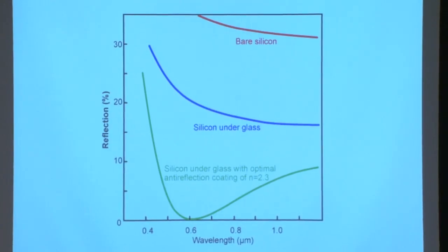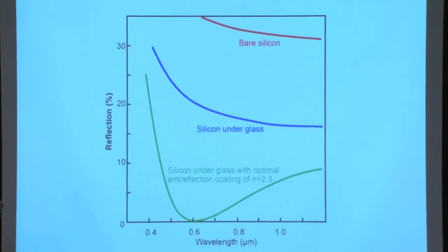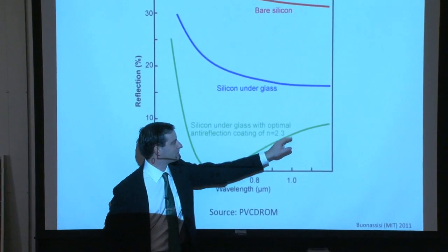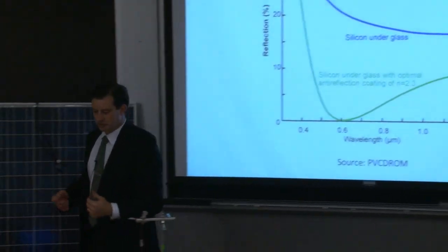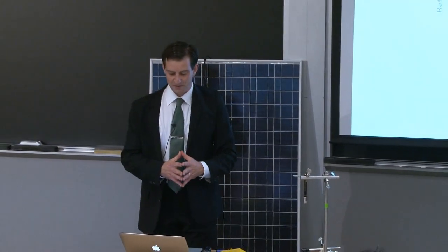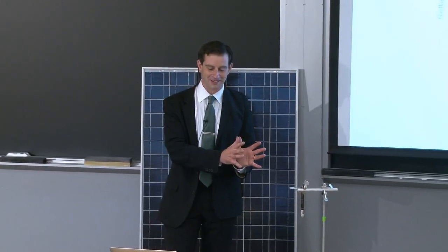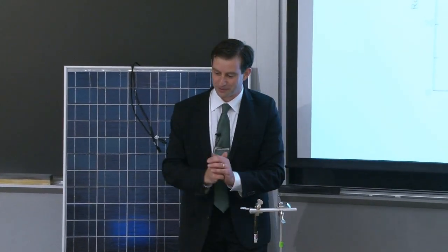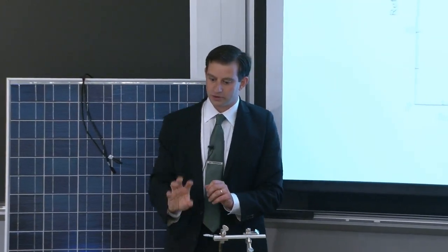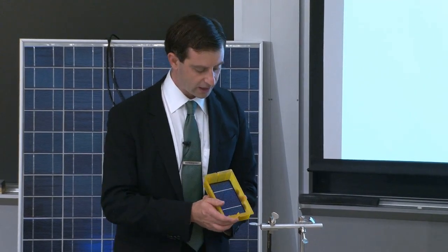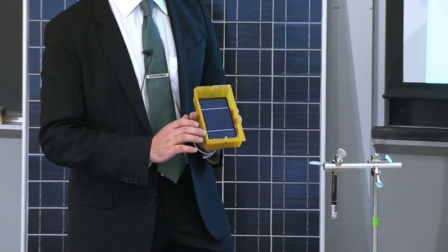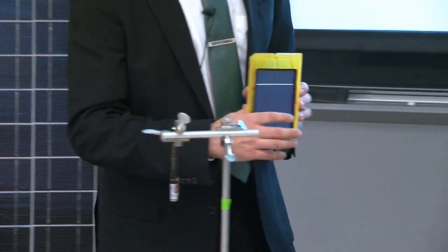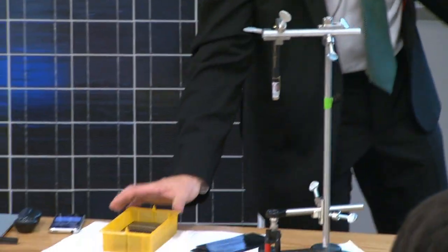So what this is saying is that you can minimize the reflection of light off of the front surface of your sample by using an intelligent combination of the very first equation that we were exposed to in the class today, which was the reflected light as a function of refractive index, so essentially refractive index matching. And secondly, by engineering an anti-reflection coating, which oftentimes in the lingo of solar cell scientists, we call an ARC, an anti-reflective coating. And those two things combined give us very low reflection off of the front surface.